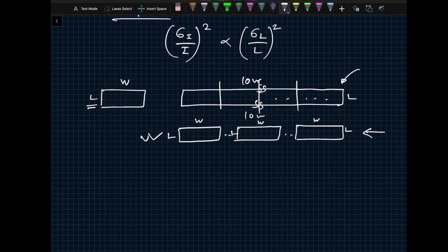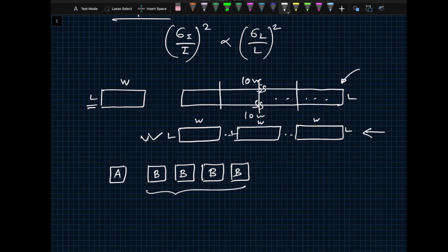You don't really lay out. Let's say there is one transistor called transistor A, and then let's say I have transistor B, which, in this particular example, let's say just there are 4 transistors. 4 units of B, right? So this is B. Then you really don't lay them out next to each other like this, because what will happen is, these guys are on one side, this guy is on one side. The statistical variation and also the slope of the oxide would be very different. And sometimes A could be a lot bigger than the unit size of B.